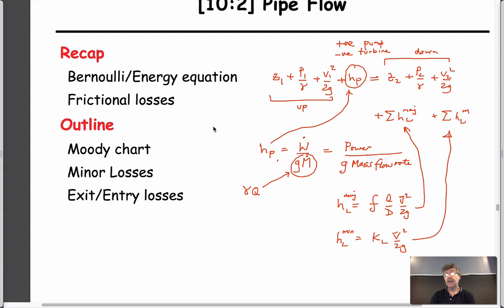And that's it. And so really all we need to understand is a little bit about the component behaviors that we have to understand to represent this friction factor. We know that flows scale with Reynolds number. And for our purposes, Reynolds number will be an average velocity, a density of the fluid, and a characteristic length. Our characteristic length is always the diameter, not radius, and divided by viscosity.